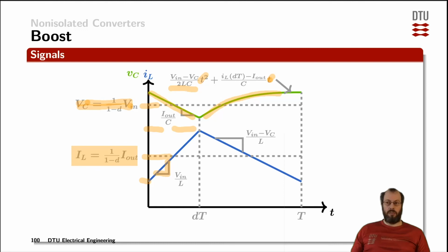During the switch conducting, we have the input voltage divided by the inductance, whereas at the off state of the switch, that is when the diode is conducting, we have the input voltage on the left-hand side of the inductor, and through Kirchhoff's voltage law, we subtract the voltage from the capacitor, which is on the right-hand side of the inductor, and again, we divide it by the inductance. This is called the dI/dt of the inductor current, and all of these variables can come very handy to calculate various operating conditions for a boost converter.